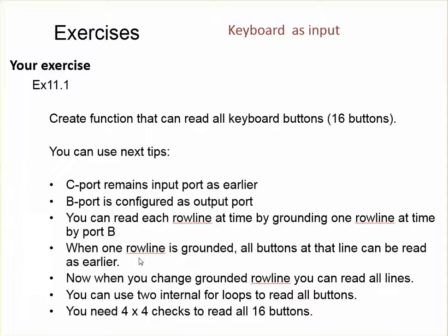And now in the first exercise we were using this manual grounding, but now we use our software through this keyboard to ground those rows at a time. So try this exercise in your own way, and in the next exercise there are more details on what kind of functionality you should be coding to read the keyboard.